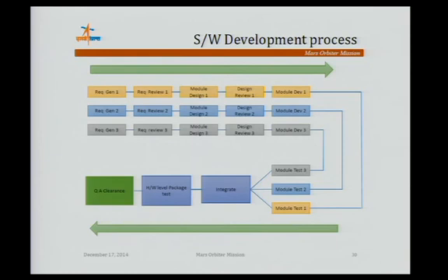This gives a brief of the software development process. It is common to most satellites, except that here there is thorough testing at the system level as well as at the integrated level, with the real system connected, so that end-to-end analysis and all the test cases have been covered. Additionally, any sequence to be executed on board is simulated on the ground and the real results are verified, expected versus observed. Only then is it uplinked to the onboard system.